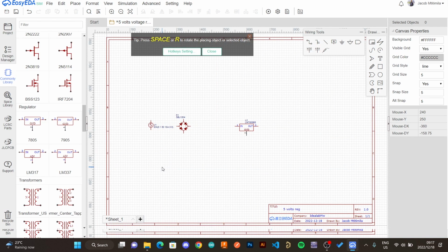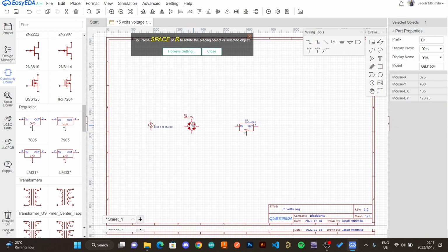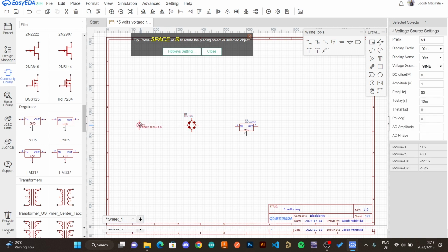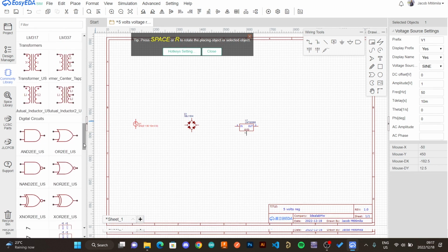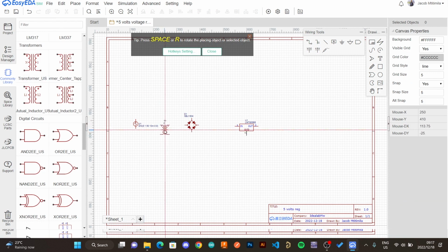A realistic way to come up with a voltage regulator with an AC to DC converter is that you need to have a transformer. You need to step down the voltage that you're working with according to the operating voltages of the diodes. So let us just have a transformer here, a basic transformer. You click that transformer, you put it here and release. Let me just zoom in a little.